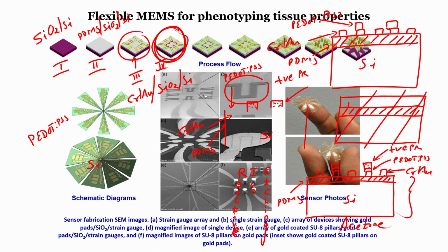So, what will happen if I apply a pressure to this particular substrate? Because there is a piezoresistor, it will bend and that will cause a change in resistance. So, we will stop our module here, and in the next module I will tell you how to coat an insulating material on this piezoresistor. I want to make it short so that you can understand just the fabrication of the piezoresistor, then the fabrication of electrodes on this piezoresistor. Okay. So, I will catch you in the next module.